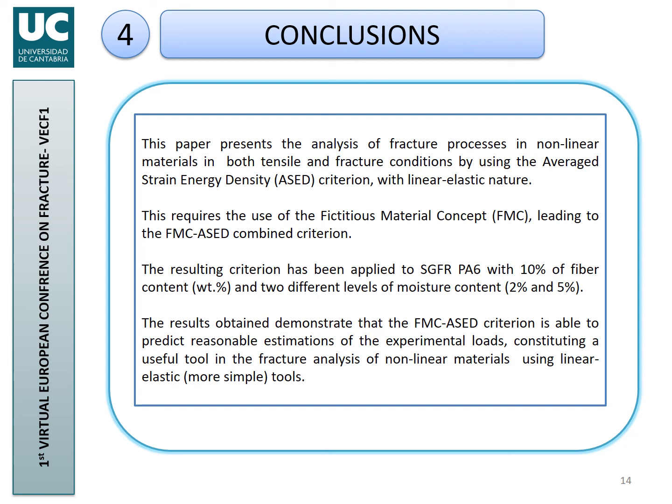The resulting combined criterion has been applied to short glass fiber PA6 with 10% weight of fiber and two different levels of moisture content. And the results obtained demonstrate that this criterion is able to predict reasonable estimations of the experimental loads. And it is then a useful tool in the fracture analysis of non-linear materials, using linear elastic and, of course, much simpler tools.